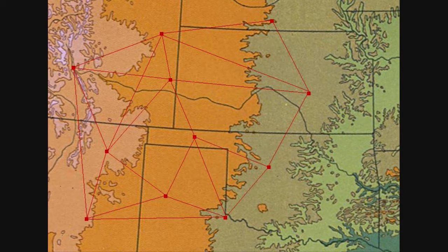Now we can see how we would travel over great distances using this. We would bounce from station to station, radial to radial. Well, in this case these are vectors because they connect to VORs, vector to vector, and we could actually get places and not get lost.